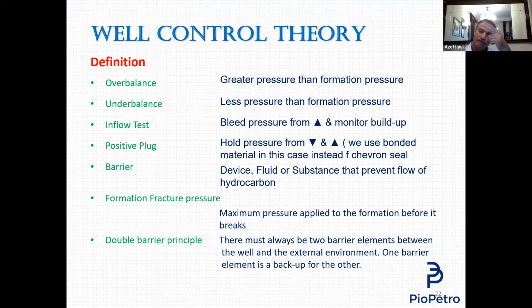Let us assume that you have two BOPs on your rig. How many barriers? One barrier. They are two BOPs, yes, but they are doing the same function. So if I put 6 stripper rubbers or 6 stuffing boxes, it is one barrier because they are doing the same function. Same function, same barrier, same body, same barrier.